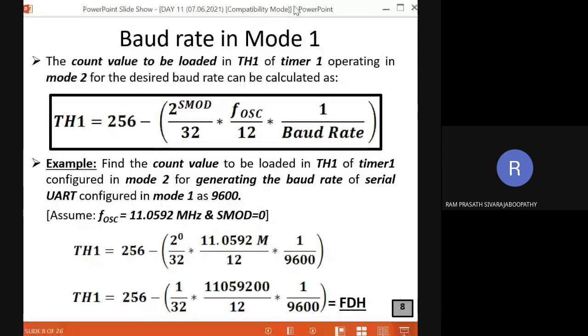It will do this function, everyone knows that. But how is it done in the program? What is happening inside that function? It's an inbuilt function available in the Arduino IDE library, so we use it directly. Do we know the nature of the UART of that Arduino microcontroller? No, definitely not. So here we are writing the program to do the same: to fix the 9600 baud rate.